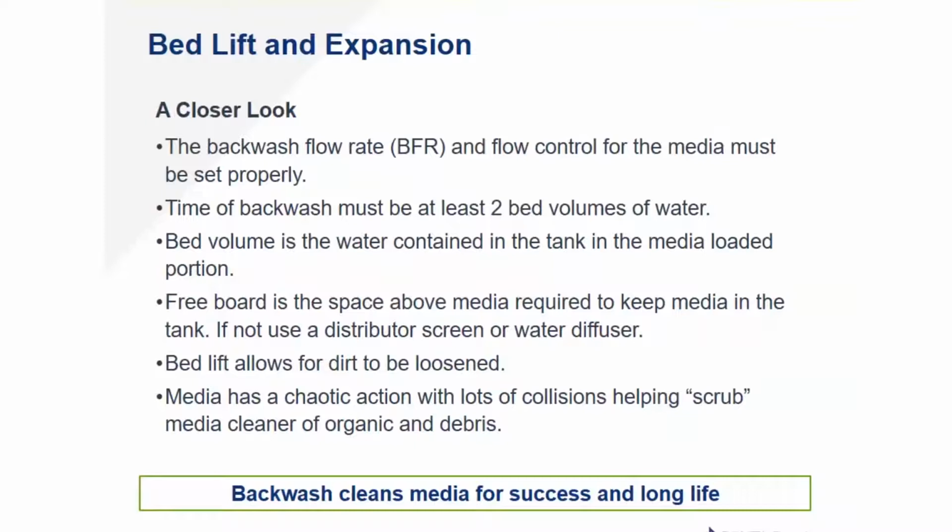Bed volume is the water contained in the tank in the media loaded portion. So the water from the media down to the bottom of the tank. Freeboard, and this is critical to the performance of a filter, the proper freeboard. Too much, we don't get the dirt out of the tank.